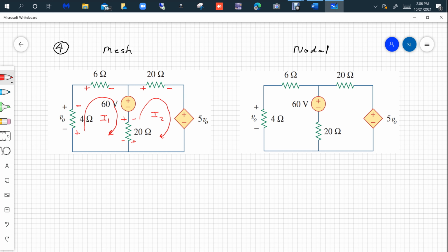In nodal analysis here, I want you to notice something very, very important. In this case, we have a voltage-controlled voltage source there on the right. And the author has given you what the voltage is for that dependent voltage-controlled voltage source on the right. It's 5 times the voltage VO, and you can see where VO is. Notice in this problem, the person who came up with this circuit is telling you the direction of current in that left branch. That person is telling you that that current flows in this direction. Has to, because of the plus to minus here.